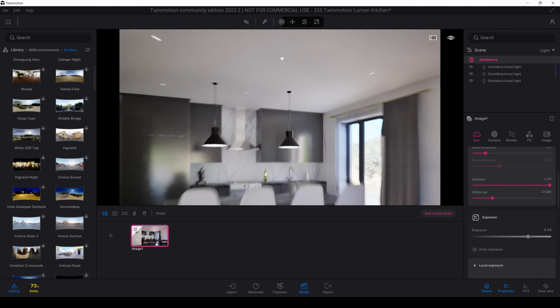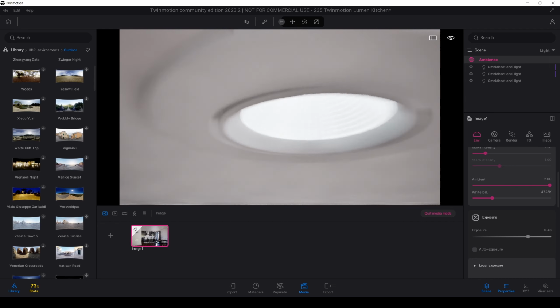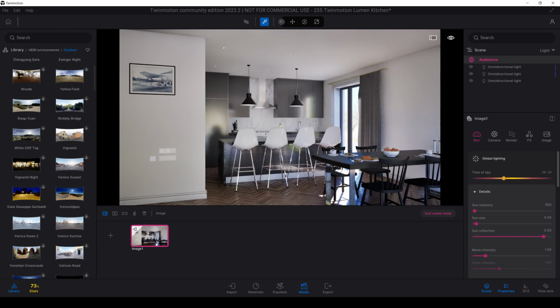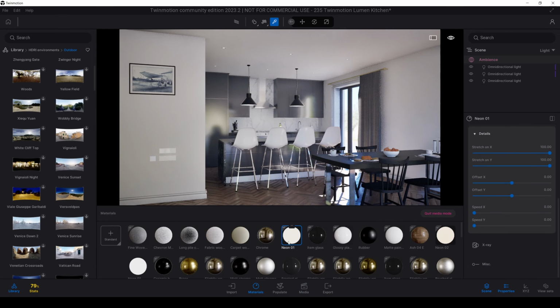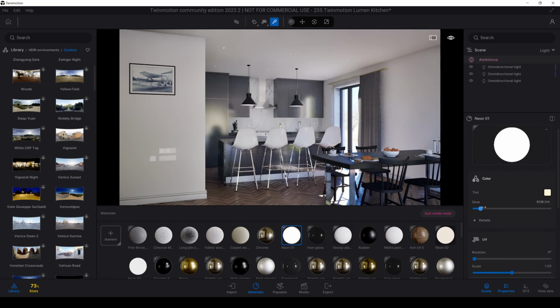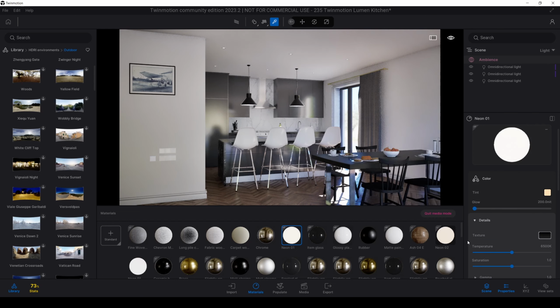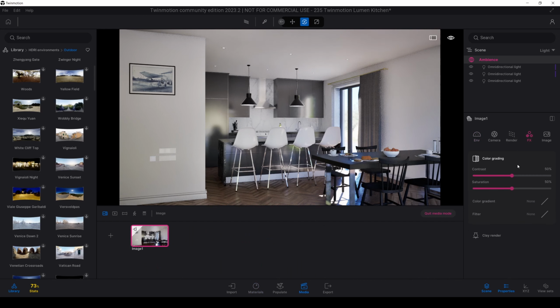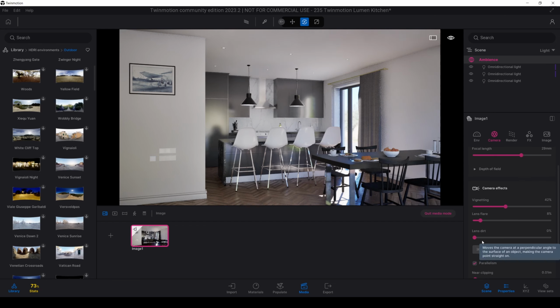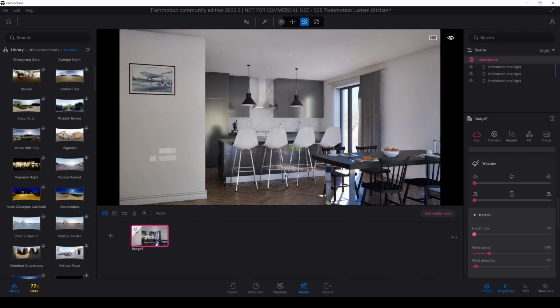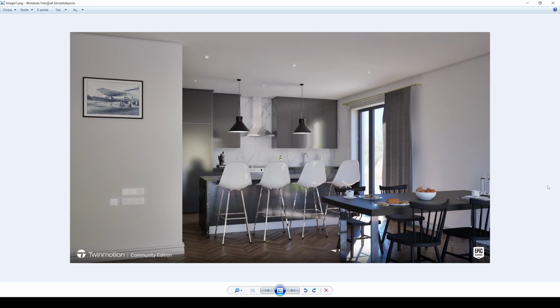As for the final small details remaining, maybe you can go to your spotlight, pick up that material, and if you cannot, you can click here, from here, change the glow intensity, change color, and much more. For the last, I'll go to FX, change saturation and contrast, vignette and lens flare. I don't want to see lens dirt in my render, and I'm gonna make this height fog 0. That's all. And this is our render.